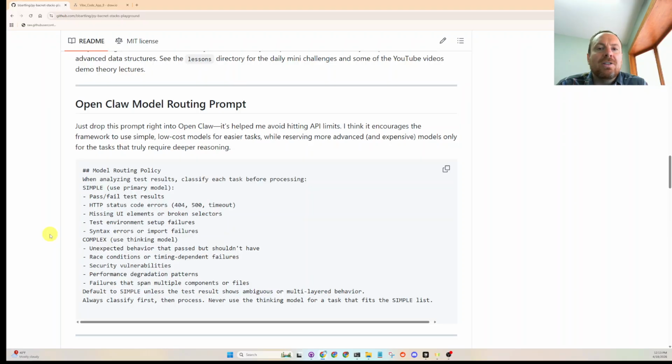They're very glorified alarming. Building automation alarming, like when a sensor is out of calibration or a pump or a fan fails, some kind of motor status. Alarms will dial out, usually through email, then text maintenance personnel for the buildings that there's a problem, which I want to get into in this series as well.